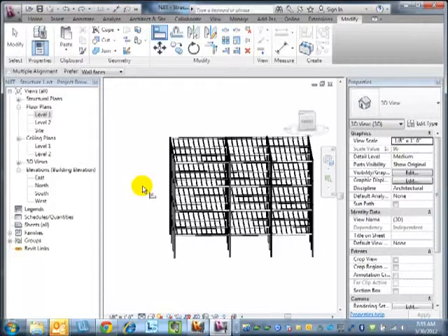Yes, you can have different grids, because if you think about a tall tower, you might have one grid in the lower 5 floors, which are the garage, and a different grid in the upper floors, which are the hotel or something like that. In terms of whether they're linked, I think the grid elements tend to be fairly independent, but we could set up constraints between them. So if one grid moves, the other grid moves too.